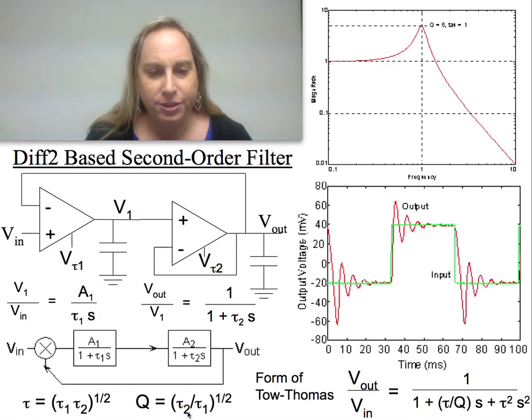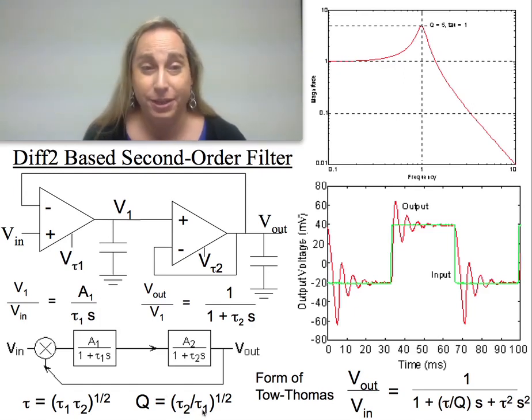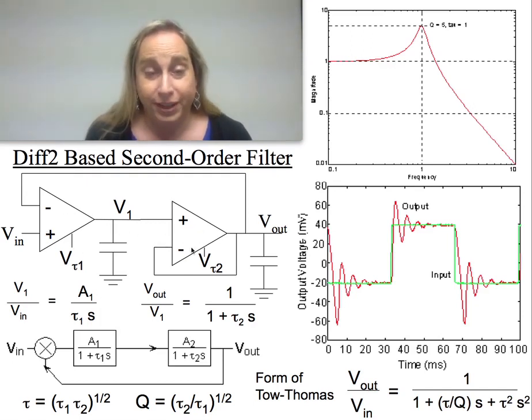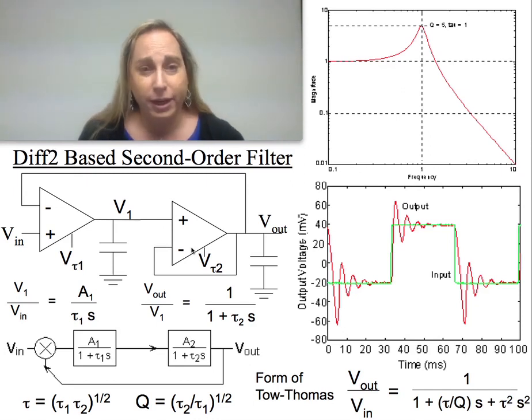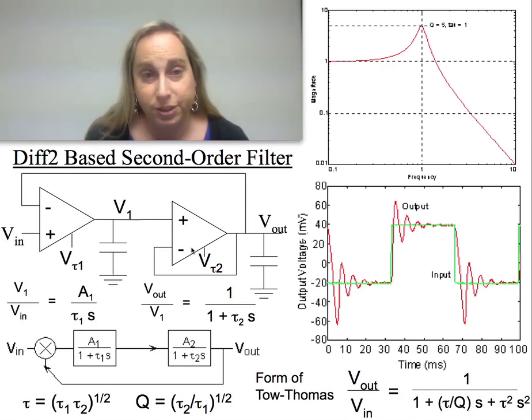The Q, interestingly enough, is related to the ratio of those two taus. That opens up some other possibilities. Certainly, if I was asking for a very simple, stable system and both of these were equal, I would be looking at a Q of 1, which gives me something at resonance. It would mean I get significantly more phase shift.